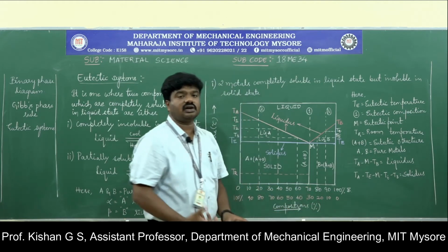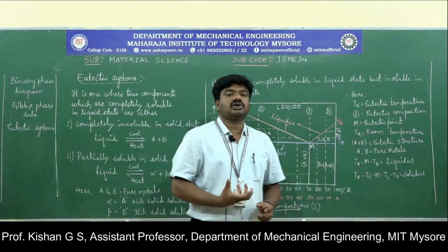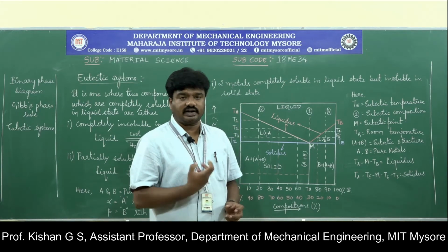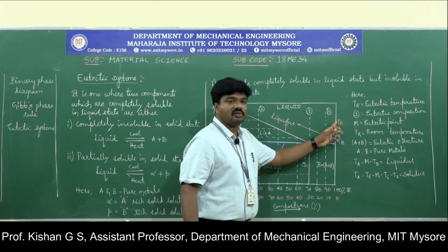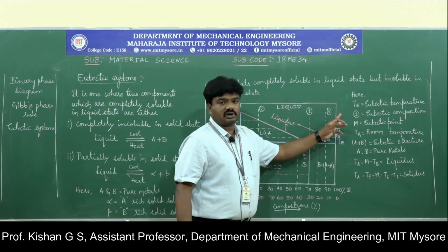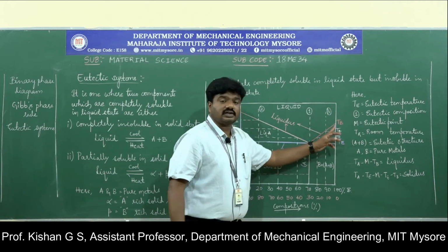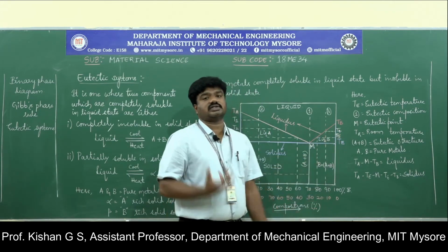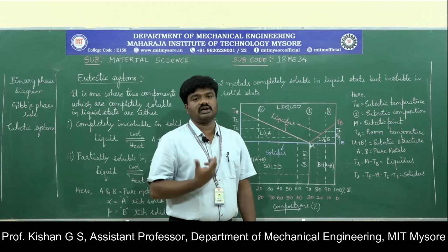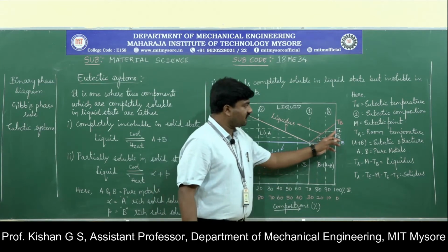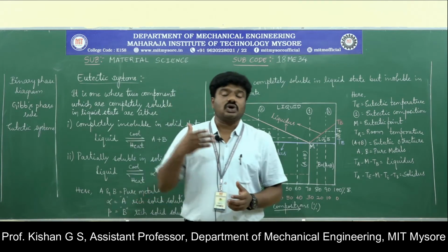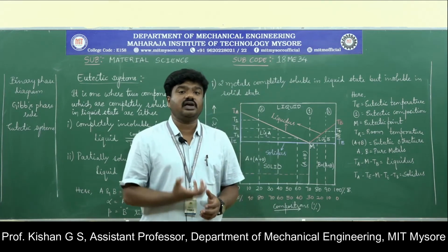Here again, what is happening? It is the addition of the rich mixture of pure metal B, which has been identified. Hence, TB is the melting temperature of the pure metal B. T4 is the corresponding temperature to the composition we have taken to assess the phase of the entire combination. What does T4 represent? T4 represents the solidification of pure metal B here.